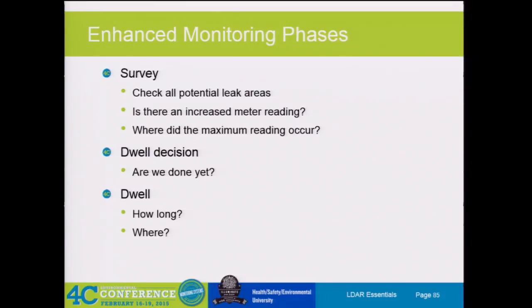So then you have to choose if you're going to dwell. If I do my survey and I don't find anything even close to being above one of my leak definitions, do I have to stay there and sit for hours? No. You just move on. But if you do get a higher reading, then you want to go back and dwell on that point and then record all of that information.